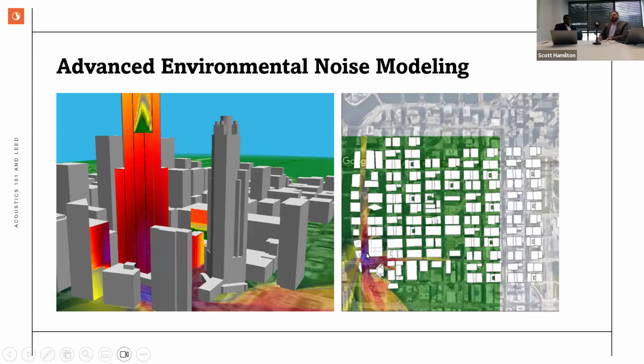But you'll see there's a higher concentration of noise level right here. It builds up, and that's because everything's bouncing around and bouncing off of these hard surfaces and buildings. And as it translates around a corner and then around a corner again, you start seeing it reaches that null level. The same thing happens here: as the distance goes up a building, you start to see the shadow zones. It's kind of fun because I think my office was right here, so we didn't get that shadow zone, but you can start seeing the colors change as you go up the building, and as you get further away, you start seeing that dissipation of sound. And this is something that we're constantly working toward: quiet environments in the urban setting, making sure we meet environmental noise regulations with a number of our clients. These are the tools, and that is the concept that we're constantly applying and looking at when we do these projects.